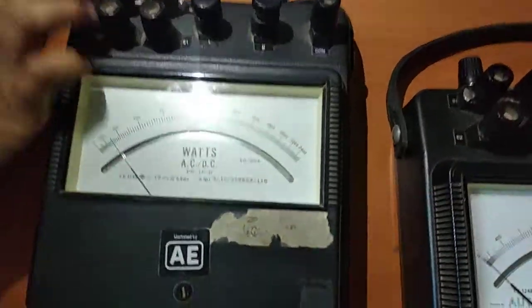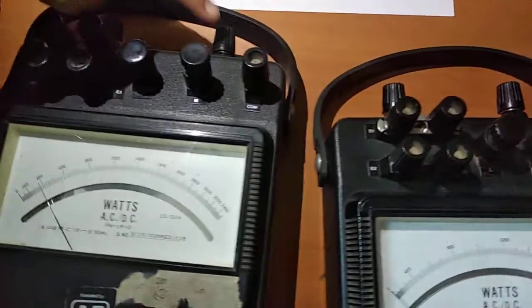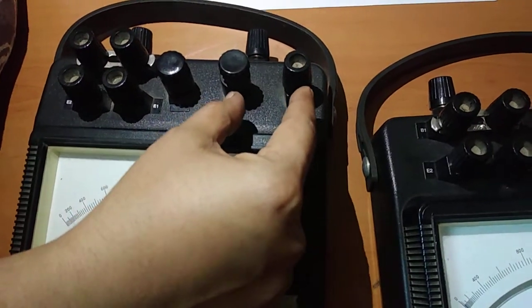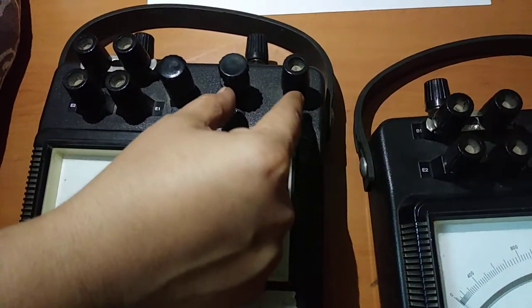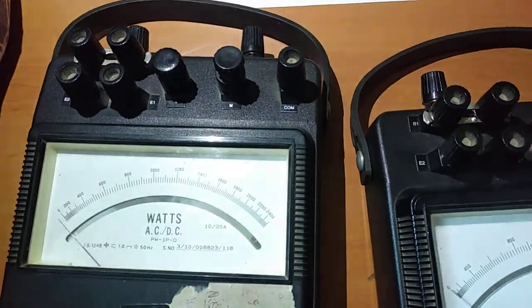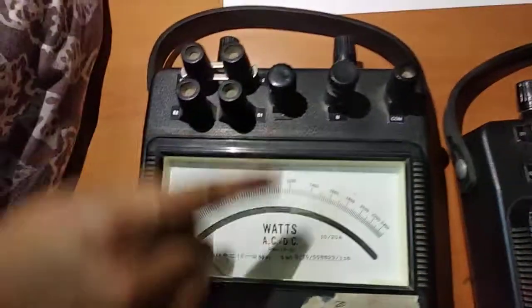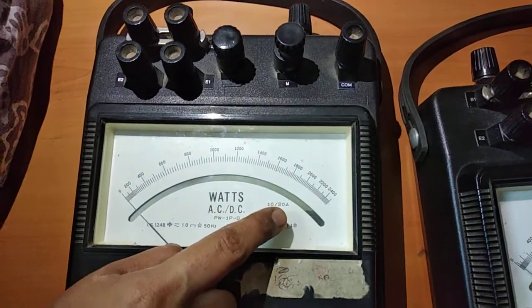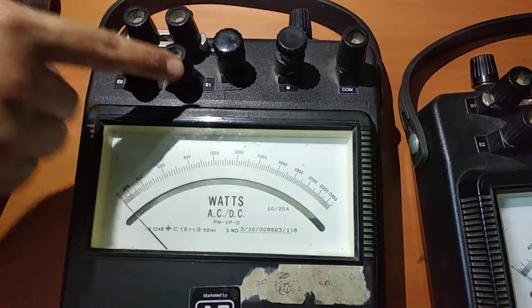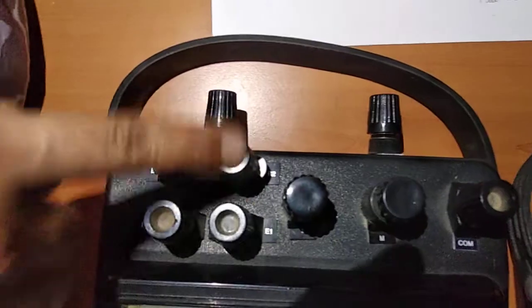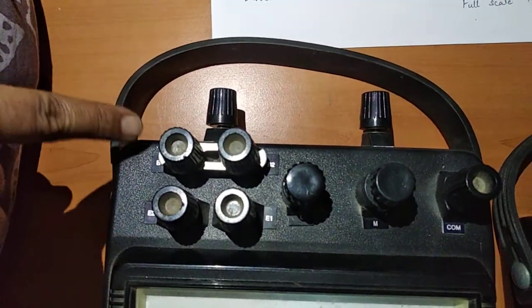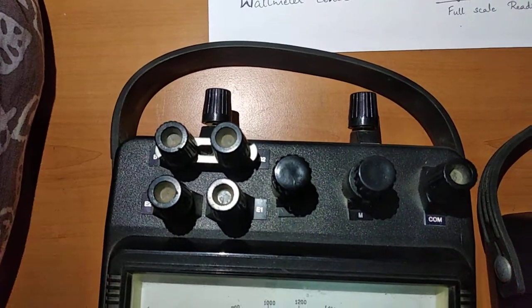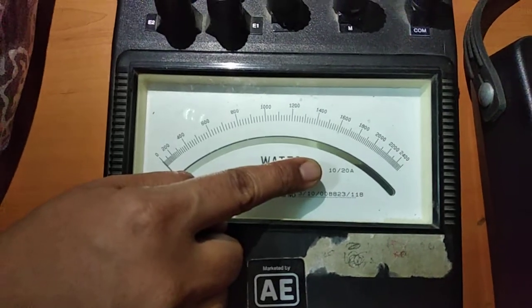And this C and V, either of them will have an internal connection, and you have to externally establish a connection between M and C, always whenever you use a wattmeter for connection in your circuit. And this wattmeter also has 2 different ranges for the current. One is 10 amperes and 20 amperes. So based on the connection here, there are 4 terminals here called B1, B2, E1 and E2. If B1 is serially connected with B2, alright, they always are used to record the lowest calibration of the wattmeter in current.